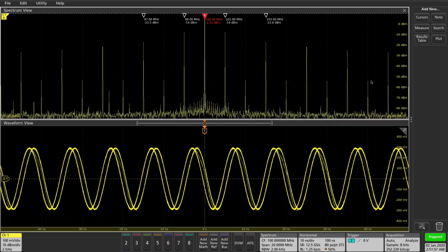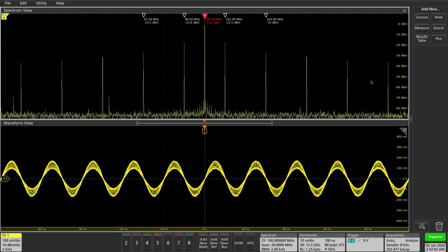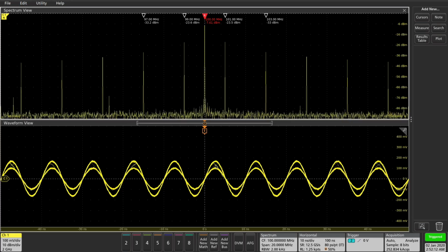Now if I change that and do exactly the same thing on the AM modulation and switch the modulation from sine to square, those tones will be missing, again for the same reason I just explained. And now you can clearly see on the vertical axis the two edges. That's because this is AM modulation. So all of this matches theory very, very nicely. The only one left is FM modulation.